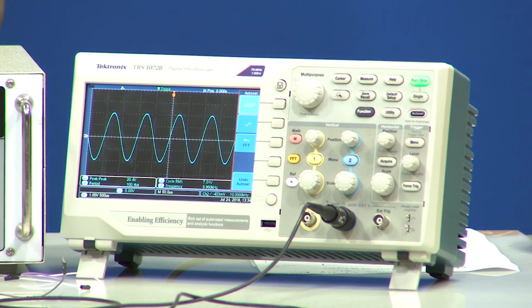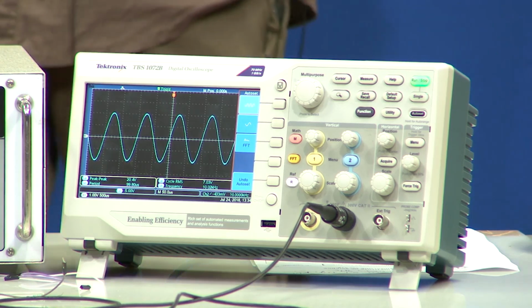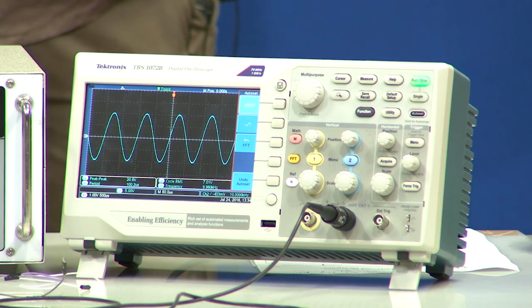So, the range of the op amp will be 0 to 26 volt peak to peak input, whereas in the earlier case this range was 0 to 12.5 to 13 volt peak to peak. This range was reduced because of the increased gain. But in a lot of applications we need the gain; we need to amplify our signal. Suppose it is a very feeble mic input, we will need to amplify the signal. So, amplification is necessary, and this is the trade off, this is how circuit design happens. For increased gain you have to sacrifice your input voltage range.